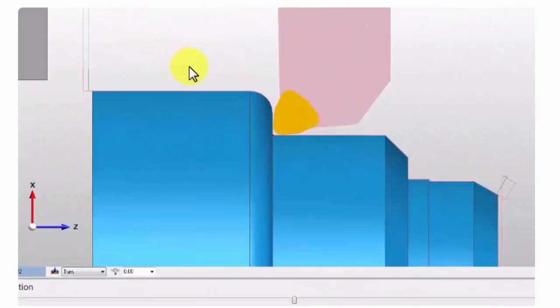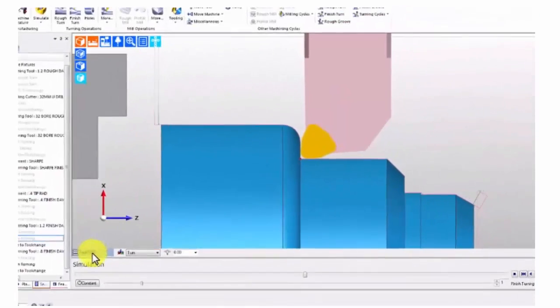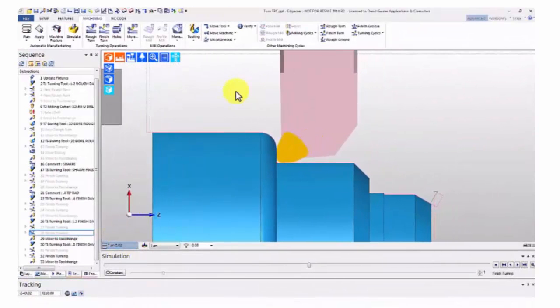It's got to be able to look at what the problem is in this tool path before it gets there, how it's got to line itself up for the next move it's going to make. And this is why it's looking ahead. And the thing to note is that when you get this alarm flashing on your screen in tool nose radius compensation, it's probably the line in front, not the line that you've stopped at.